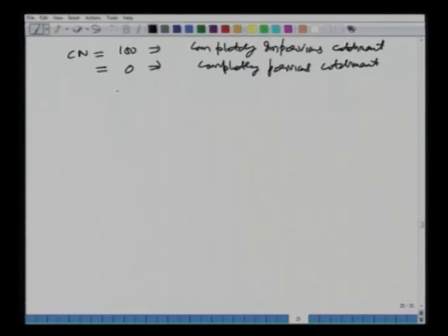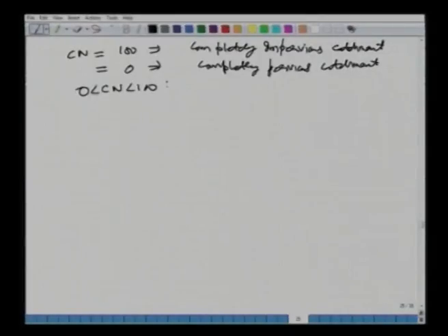Normally the curve number would be between 0 to 100. When the curve number is close to 100, we are saying the catchment is completely impervious. Impervious means there is hardly any infiltration. It does not allow the water to infiltrate. What kind of a catchment would that be? One in which there are lots of buildings, roads, parking areas, streets. All of those areas will not allow the water to infiltrate. So, if you have any highly industrialized catchment, the curve number will be high.